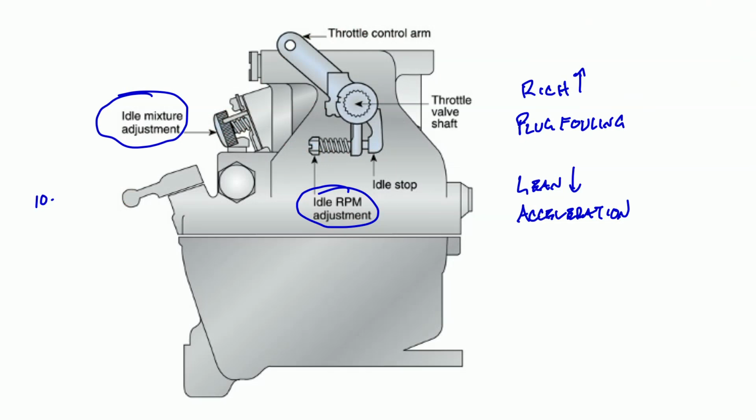So if we find that our idle mixture is off, we're going to note that through what the engine's behavior is as we try to shut it down. Now, there's two ways to do this. We can either shut it down each time and watch, or if you're quick on the mixture lever, what you can do is pull the mixture lever back further and further and further all the way to idle cutoff.